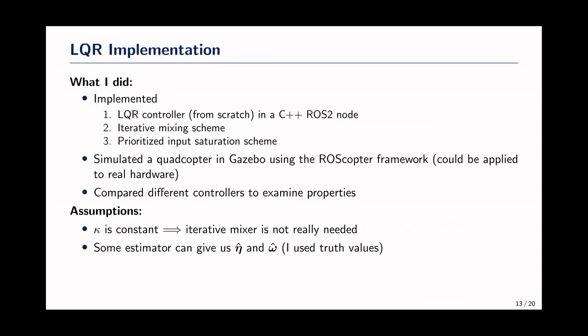In my implementation, I implemented LQR from scratch, including solving the ARE in a C++ ROS2 node. I implemented the iterative mixing scheme, and I implemented the prioritized input saturation scheme. I simulated it all on a quadcopter in Gazebo using the RotorS framework.